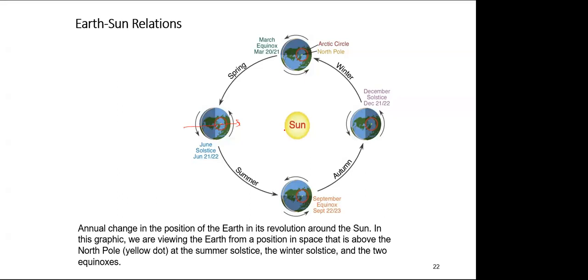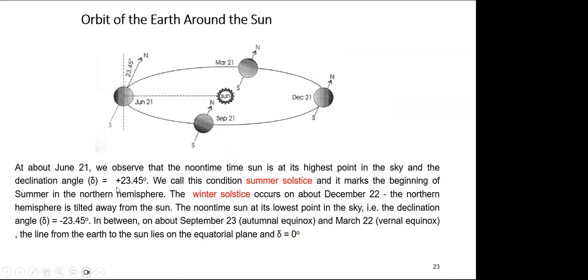If you check your calendar from 20 years back, maybe it was April 12 and 13, and now maybe the 13 and 14. That is the reason, because one year is maybe not exactly equal to one rotation of the Earth. This is also a very important factor when we work out the Earth-Sun rotations, because of solar tracking and everything. If you want to find these angles, we have to consider even very small variations. Then there is some further explanation here. We call this the declination angle.